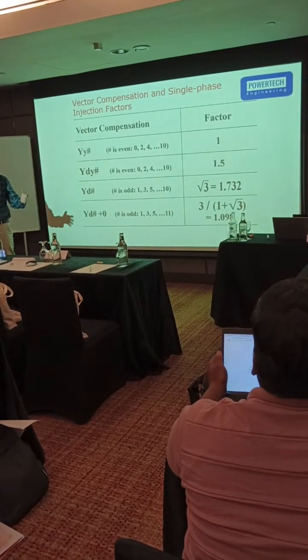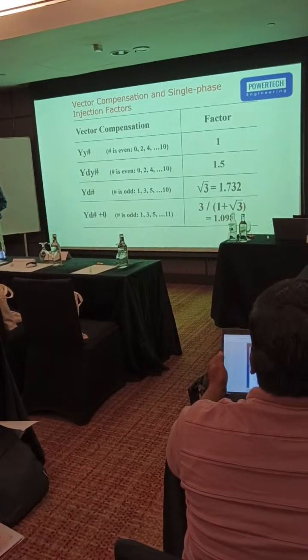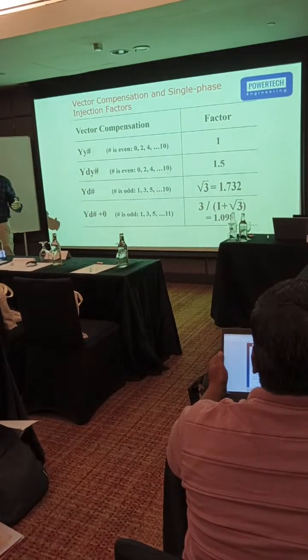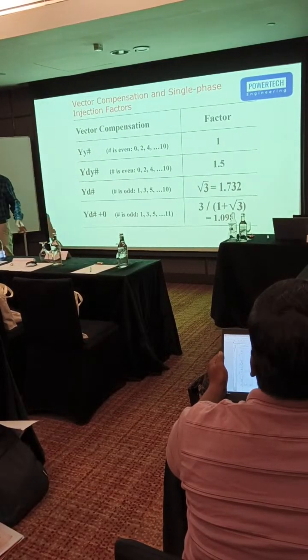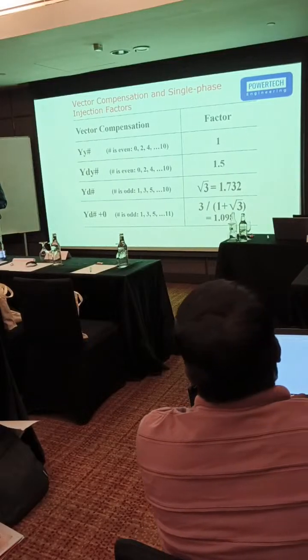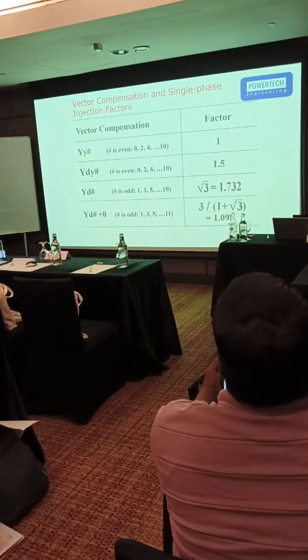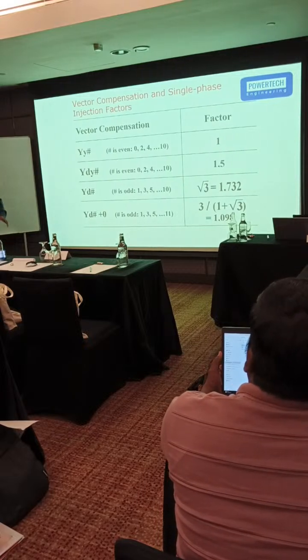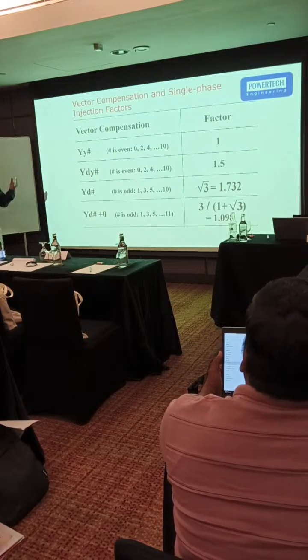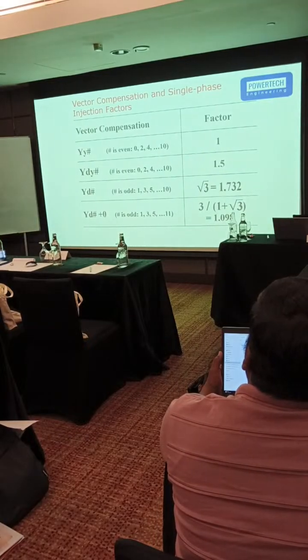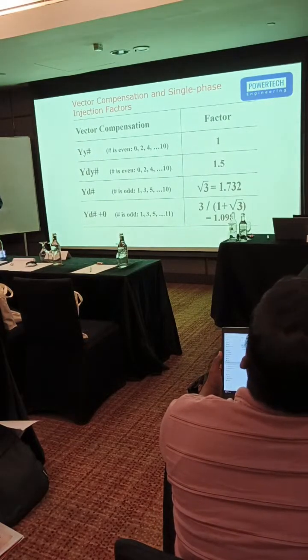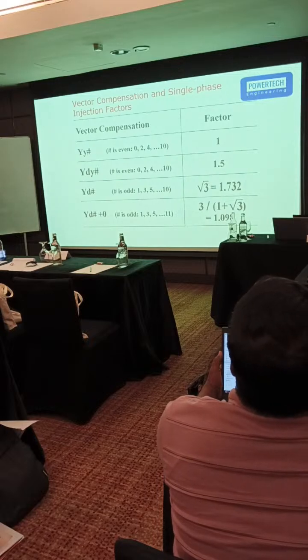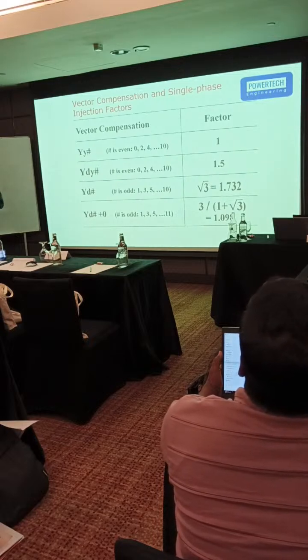So tomorrow we have a hands-on on the relay. On the relays we will also explain, not all combinations, but at least the two which are very common: delta-star and star-star connection. So we can demonstrate all these things, how to test the differential relay. We can create this test plan manually as well as with the help of a template, so that you can understand all the points.